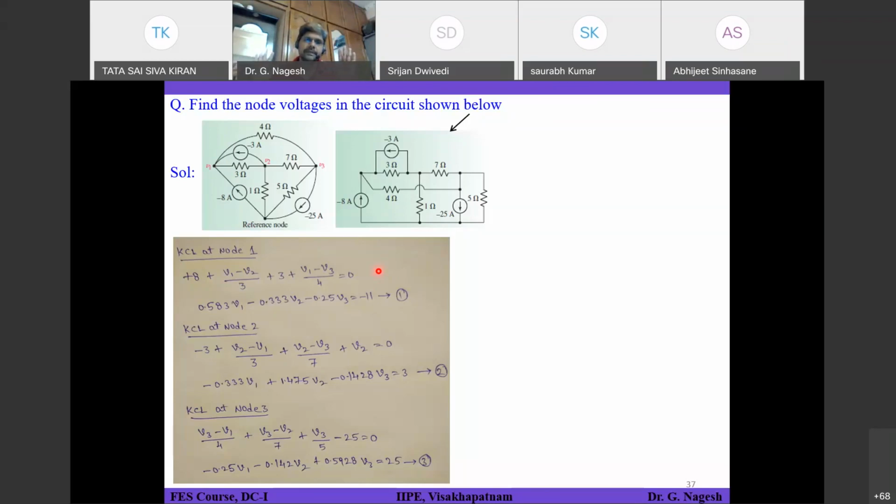But I am going to teach all problems with respect to this convention, all the currents leaving that particular node, so that we both will be in sync and have the same conclusion. So try to write the current leaving that particular node whenever you apply nodal analysis or KCL. That will avoid your confusion.